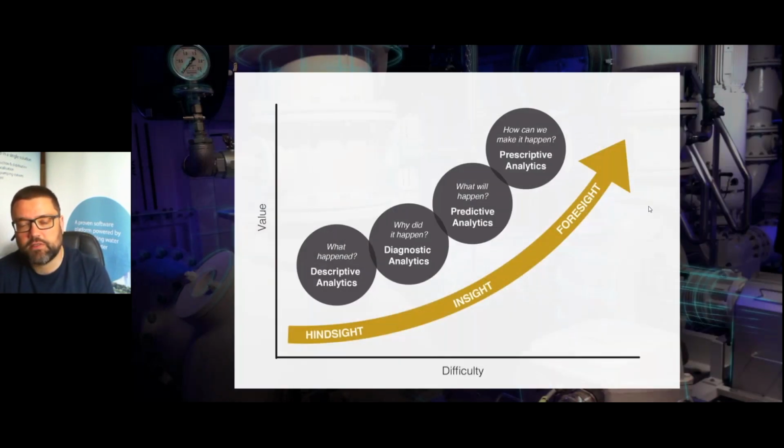This is a typical data science curve, and it really highlights what Christoph just touched on. Up to maybe the last one, two, three years, sensors in sewers have tended to be put in to monitor combined sewer overflows, CSOs. That's what we would term descriptive analytics. It's telling the water utility what did happen. It allows them to report to the regulator to say, yes, we spilt, apologies, but it was raining, so it's allowed.